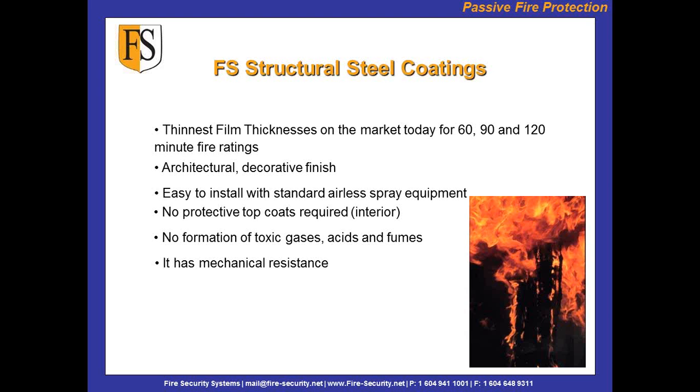So with our thin film coatings, what we've found through a lot of cross-sectional work with other suppliers is that our film thicknesses are extremely thin compared to the competitors, especially at 120 minutes. In some instances 30 to 40% thinner. And this comes back to what we discussed in our first seminar with FS15 cable coat: less product, less freight, less storage areas.